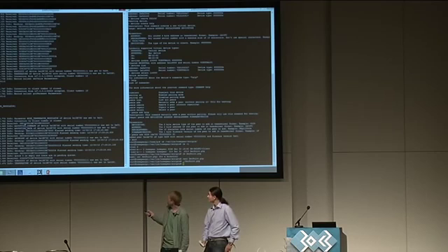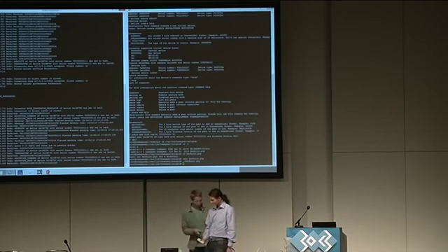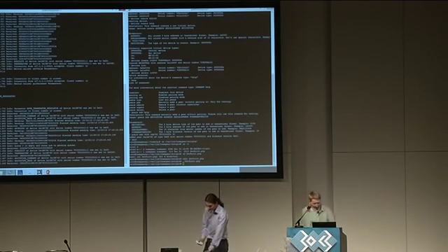This is the packet sent from the thermal control to the valve drive, and after this packet, here you can see the set point temperature being set, the configuration start packet, the setting of the mode to central mode, and the configuration end packet. Okay, now I'm switching to the webcam again.